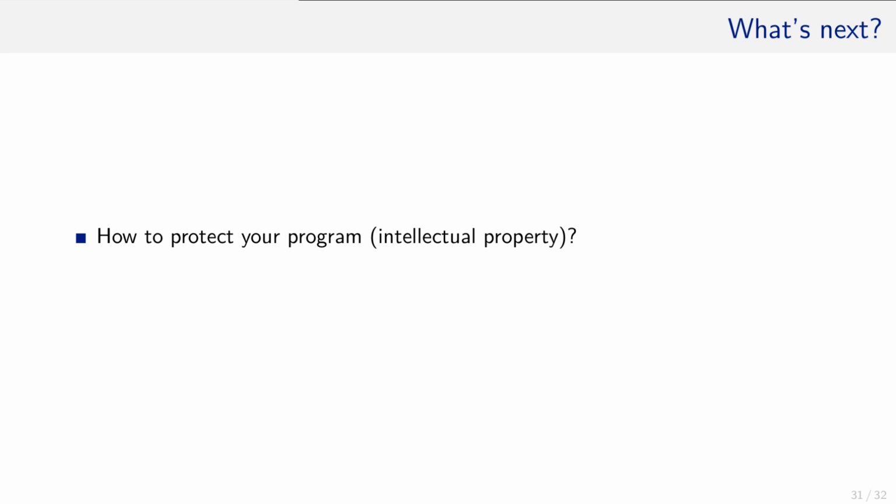And what is next? In the next chapter, we will talk about one of the last steps in the development process. Once the implementation is complete and tests passed successfully, your product is ready to be shipped out to the customers. A lot of efforts were put into the development, and you might want to protect the implementations against spurious analysis tools and disassembly. The ATmega has a fuse to lock the flash so that its content cannot be downloaded any longer. How to set that fuse and what needs to be considered will be the topic of the next chapter.